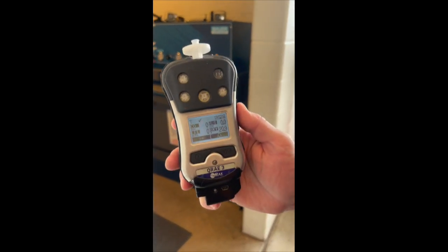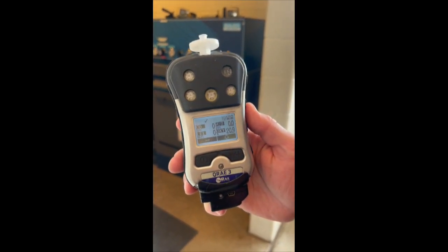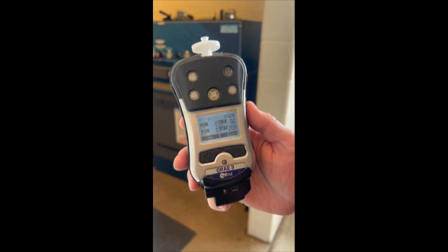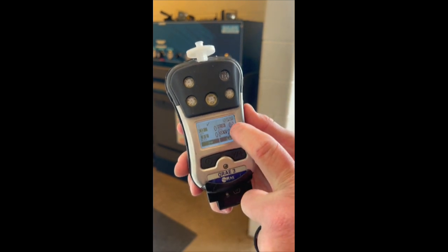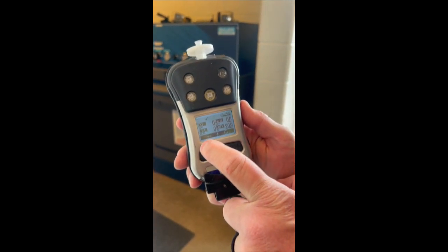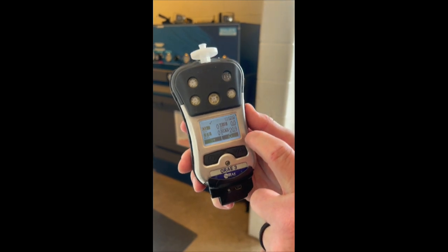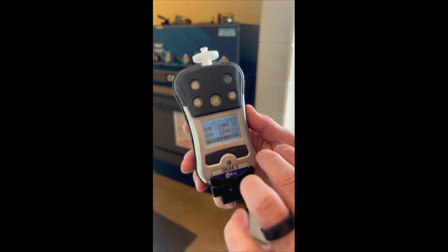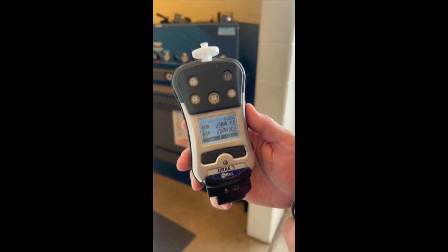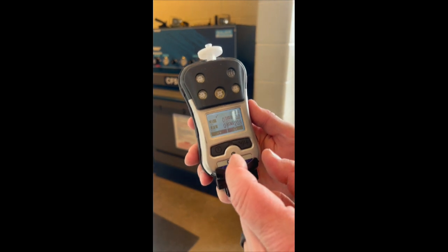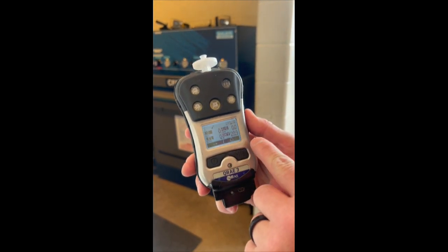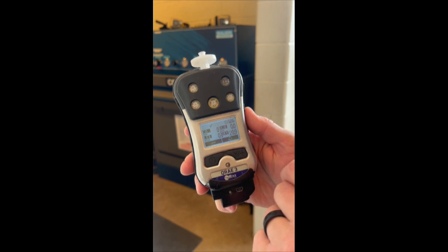So in this case, we're talking specifically about our Q-ray CGIs. And our CGIs, the manufacturers may have changed for some of them, but what they read are the same. The CGI, the combustible gas indicator, has two toxic sensors, which are carbon monoxide and hydrogen sulfide. And then it has the LEL and the O2. The LEL works in combination with the oxygen sensor because it needs a little bit of oxygen in order to read if an environment is flammable or not. So it's important that the oxygen is also correct.